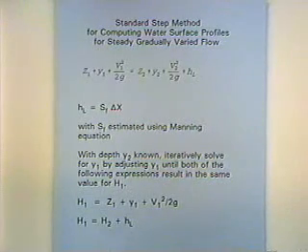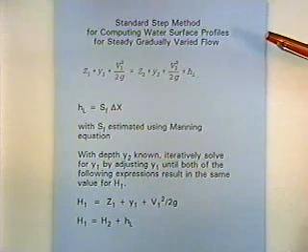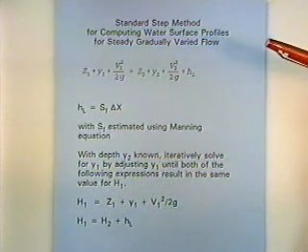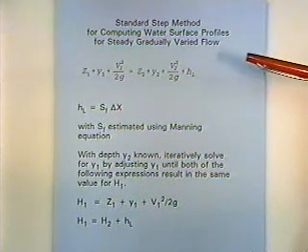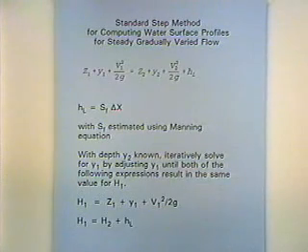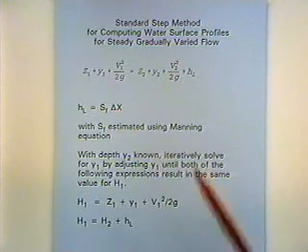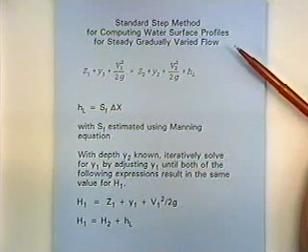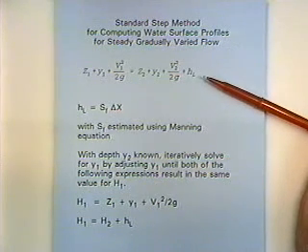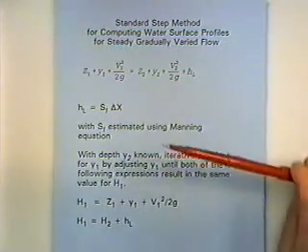And so this is the same thing almost, but the computations are a little different. And this is the HEC-2 approach, or all the different water surface profile computer programs do this. And so we call this the standard step method for computing water surface profiles for gradually varied flow. Energy equation hasn't changed a bit. Same old energy equation we've been working with before.